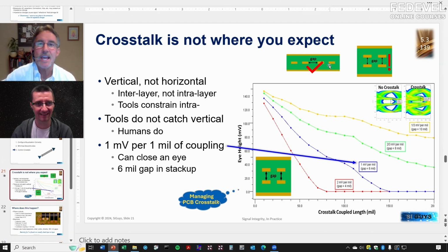Clearance. Yes, yes. So this number, people set that to 25 or 30 mils and then they don't worry about it, right? And it keeps all your traces so they're not crosstalking sideways. Okay, but here's the gotcha. This is where the problem is. Tools don't check that. You'll see what I mean in a second.